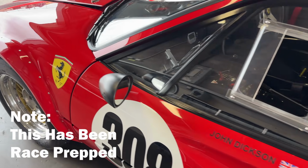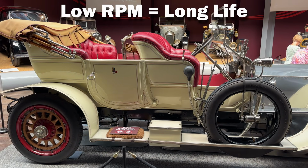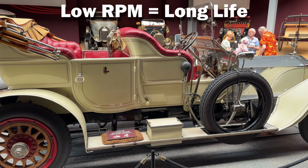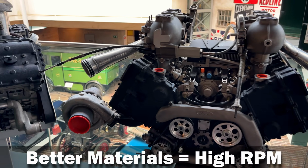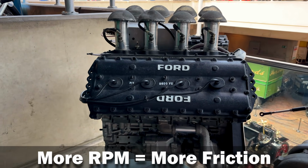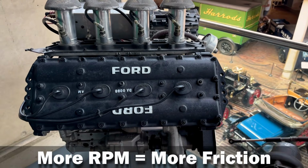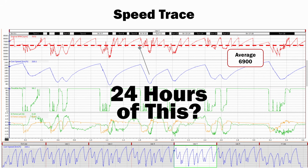Now, it also has some pretty big implications on the engine life. In a road car, you want your engine to last a long time. So we want to keep the revs pretty low. In the race car, running at these higher RPMs has pretty big implications. It means we're going to need stronger materials. We need a better balanced engine. We've got to think about the kinetic energy of components. Friction and the oil leads to RPM dependent friction. And if we're doing long distance racing, the best sort of racing, you could have 6 or 12 or even 24 hours of hard load. Now in a 24-hour race, you could be doing 4,000 kilometers of high load in a GT3 car.